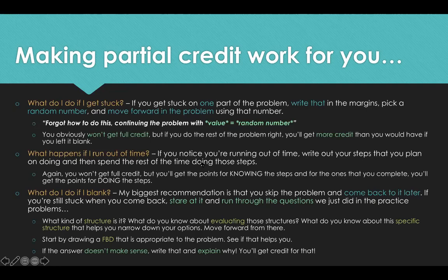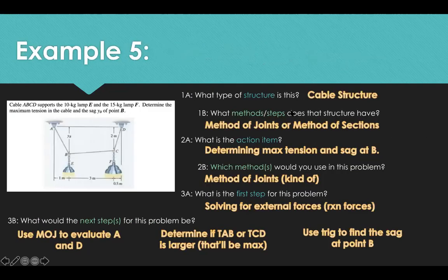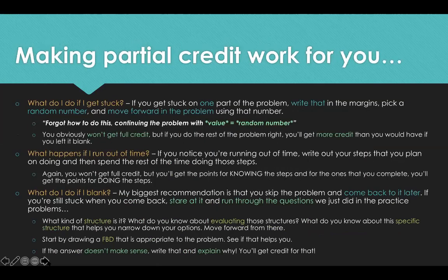So I guess the last thing to cover is what happens if you look at a problem and say, I don't even know what the heck to do. I don't even know where to start. I would literally just run through the questions from back here. What kind of structure is it? What steps does that structure have? What is it asking me? How can I get from the steps that I have available to me to a final answer? I would go through that kind of stuff. Always start with a free body diagram, because maybe you're just not seeing something 100% of the way.